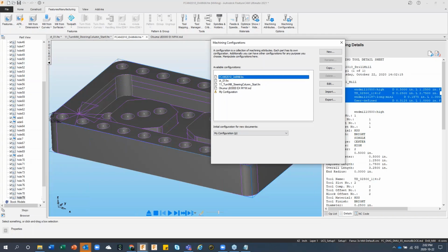Okay, so I can have different configurations for different machine tools. I can have different configurations based on material or the family of parts that I'm programming. Okay, so if I have two 3-axis mills side by each, one of them is a 12,000 RPM 40 taper racehorse machine, and right next door, I have a 60 taper, 6,000 RPM spindle. Those two machines are mechanically capable of doing the same operations, but you drive them completely different.